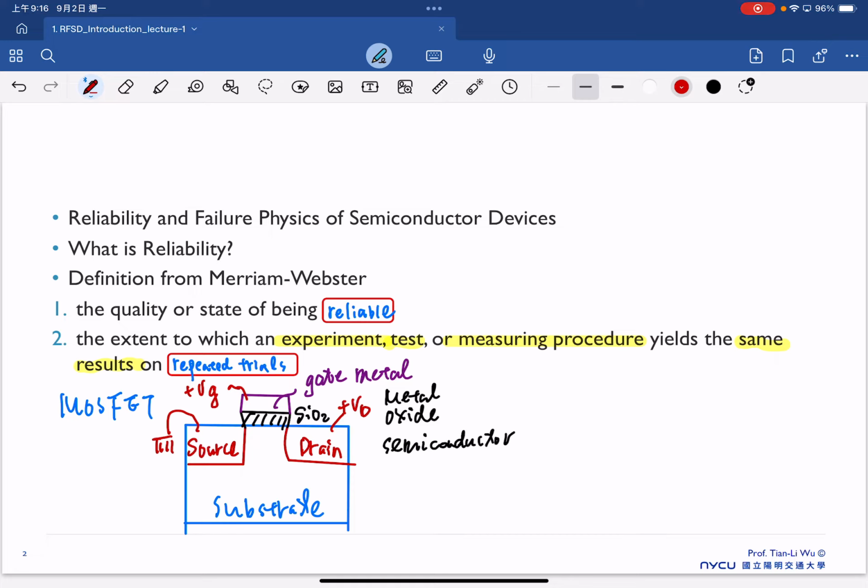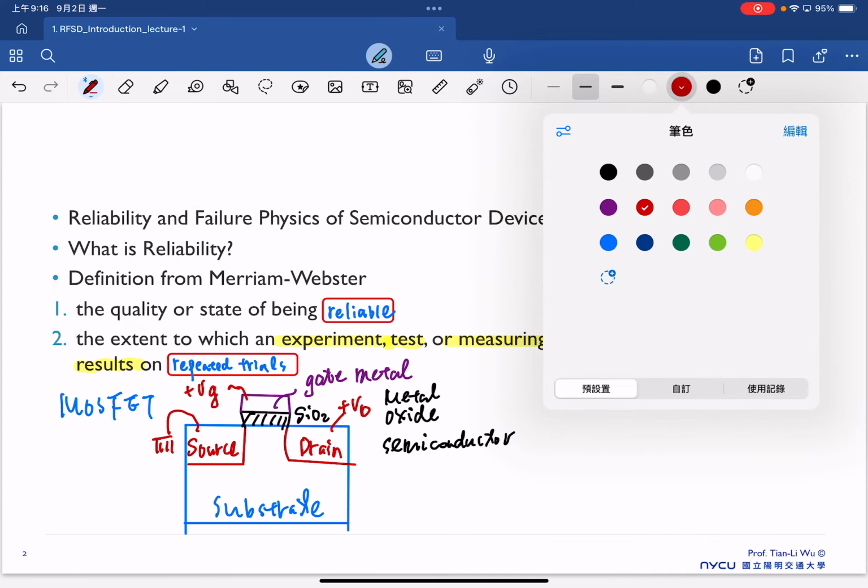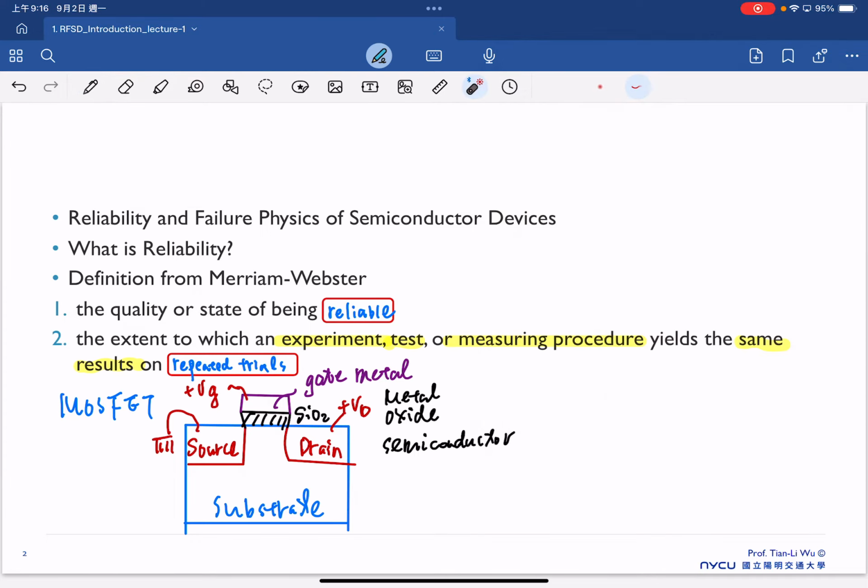Okay, so in this device, we will bias the drain side, and in the meantime, we'll apply the gate voltage. Since we apply the gate voltage on the top metal, we can imagine that the positive gate bias will start to attract the electrons here. After a certain moment, we can imagine some negative electrons can be formed under the gate dielectric.